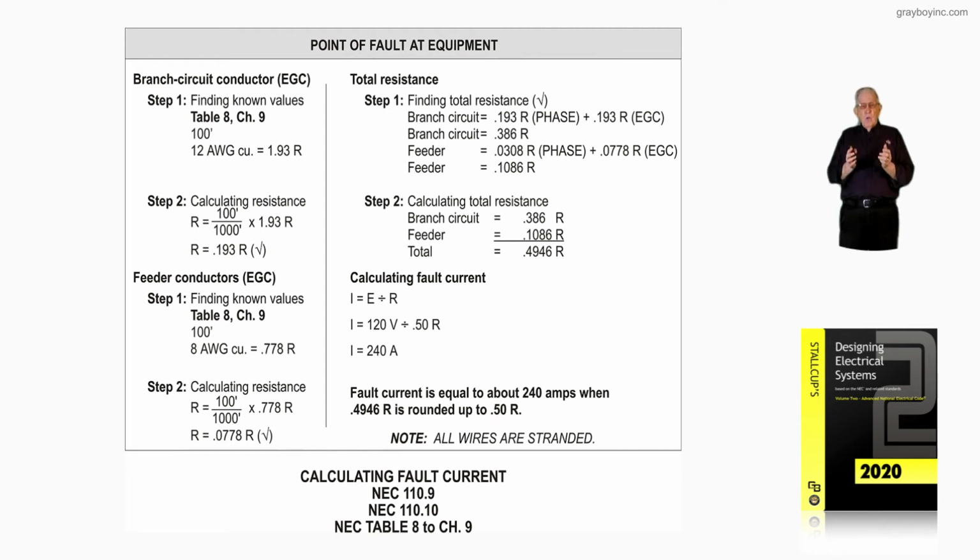But because you can use your code book and do this, and just use your iPhone with this calculator to do that. And if you got one of those iPhones where you could build in your formulas, I know you can get a little handheld calculator from TI to do that. And then all you have to do when you put the formula in that you see up there, just put your values in, it'll tell you right quick. Or you just say, no, this panel board is 10 kA, and all my breakers in there and equipment is 10 kA or less, then you know you're going to interrupt it.